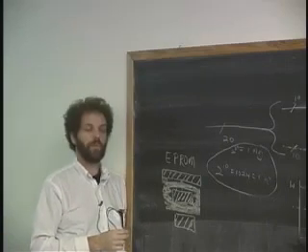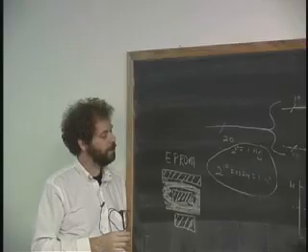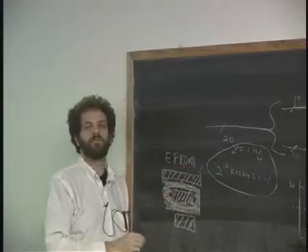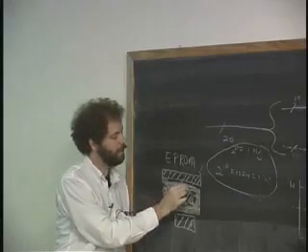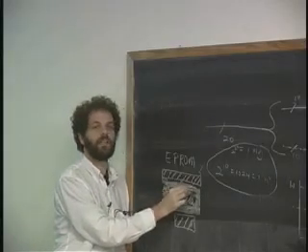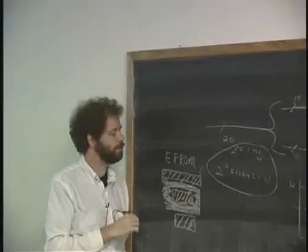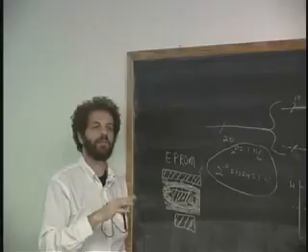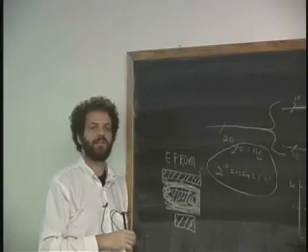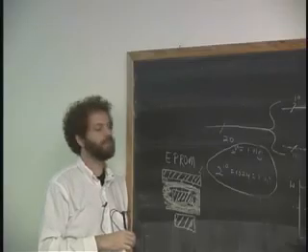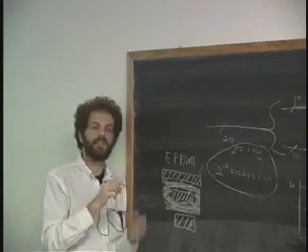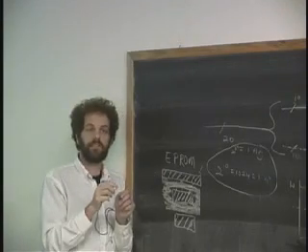Anyway, that's one way to do it. And it turns out that another way to do it is if you shine ultraviolet light through here. The ultraviolet light excites the atoms in the glass, and they turn a little bit into a conductor, and the charge leaks off. So it makes the glass not quite so good. Only while the ultraviolet light is on. So in general, these chips can be erased with an ultraviolet light, and you see some of them with a window on the top that has glass, right?